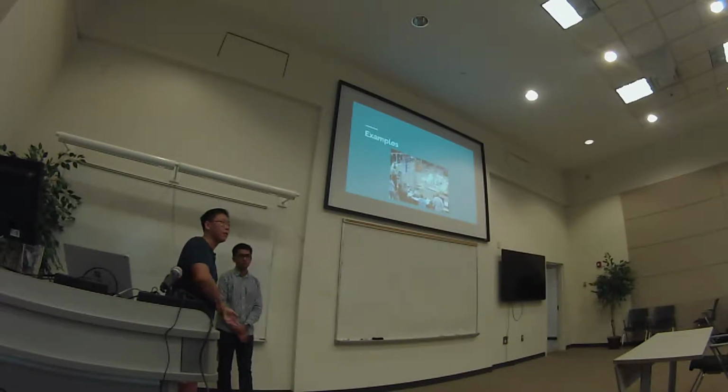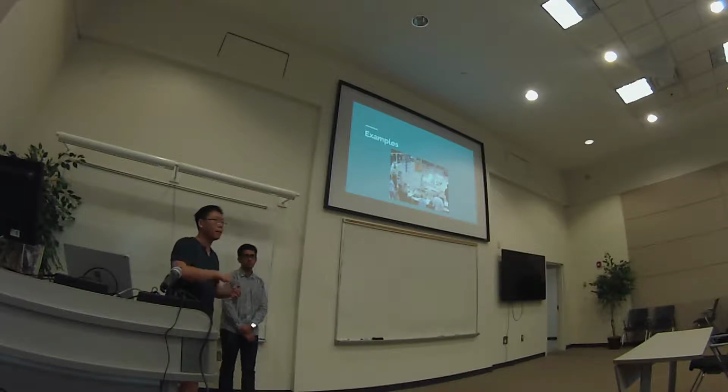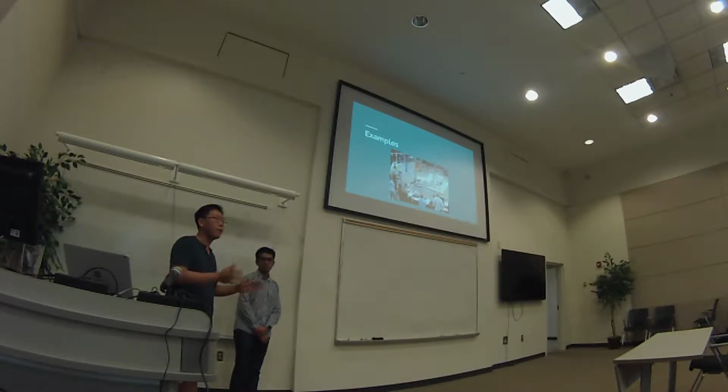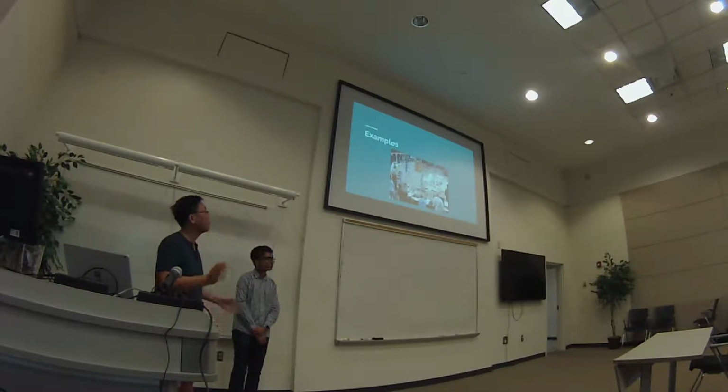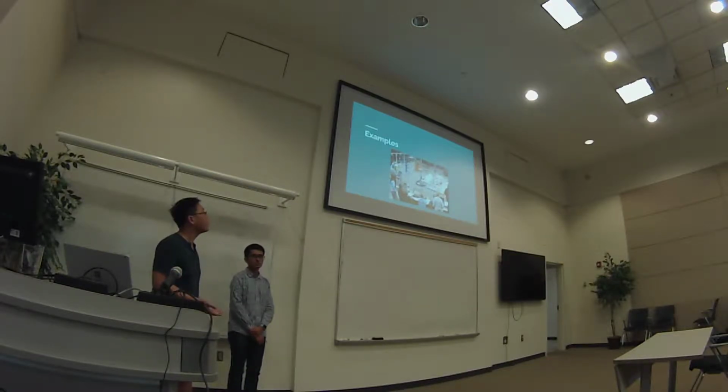So let's say you want to turn 90 degrees. That would be your set point. And then you measure the error between your current angle and the set point. And then your PID controller computes the appropriate output, again, to deliver to both sides of your robot in order to rotate. And then the same thing is true for their elevator, where they